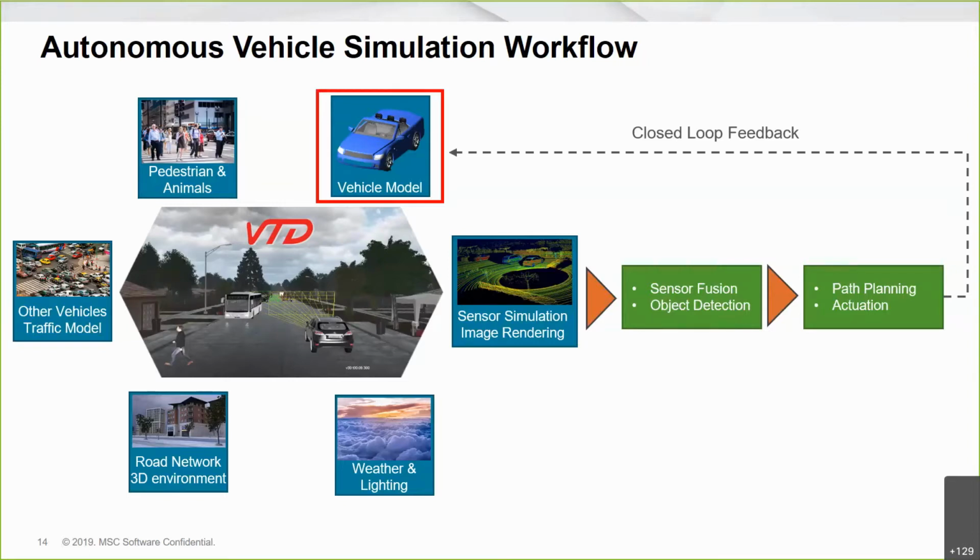The complex suspension system, and how you take stiffness and damping coefficients into account, how the chassis and the steering are going to react. When you are working with those more complex issues, and if you want to see how sensors are reacting to that, then you will need a more complicated vehicle dynamics model, and that's when Adams Car comes into play.